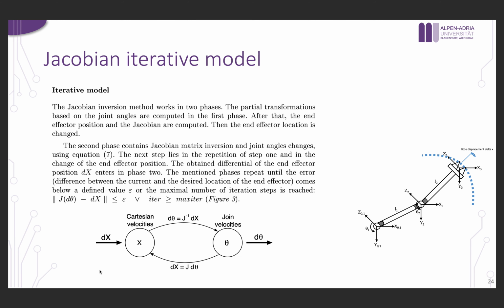So what I need to do now is repeat this iteration again, until I make this error as small as possible. What do I mean by that? We always have the target speed, right, which represents the movement along a path. Now for this target speed, we can use the inverse of the Jacobian matrix. We can get the change of theta that I need to apply on the joints to move the robot arm with this angular velocity, for example.